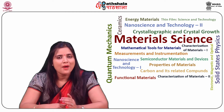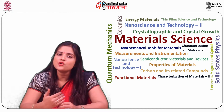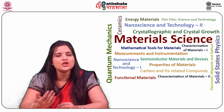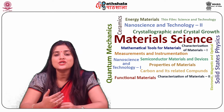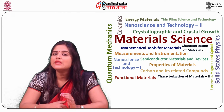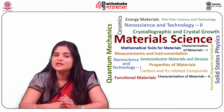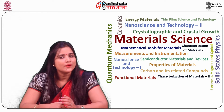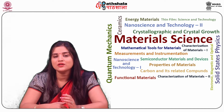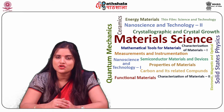Thus, when an op-amp is operated in the open loop configuration, the output either goes to positive saturation or negative saturation or switches between the two saturation levels. This limits the use of open loop configuration for linear applications. However, they can be used in nonlinear applications such as square wave generators, etc.